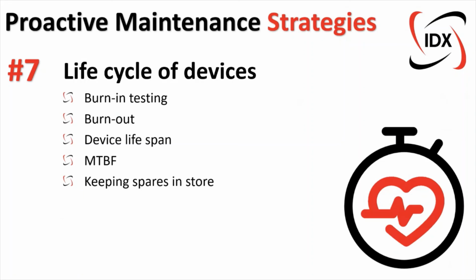You should also train staff up and at least know how to configure and program these devices when you need to replace them. For your PLCs, ensure that you have a backup of your PLC program stored on file. And this is excessively important for legacy type devices where the original system integrator or PLC programmer might not have that spare for you. So when you need to replace a PLC and you've lost your program, it's going to cause quite an expensive rebuild.